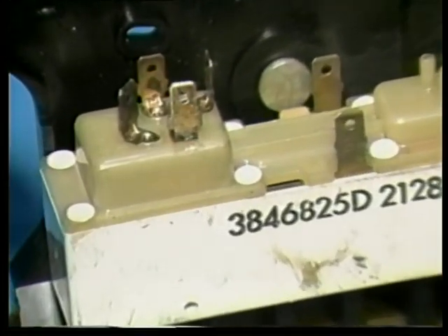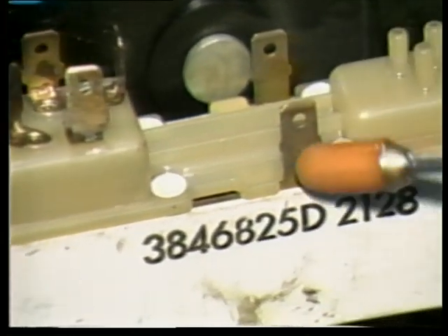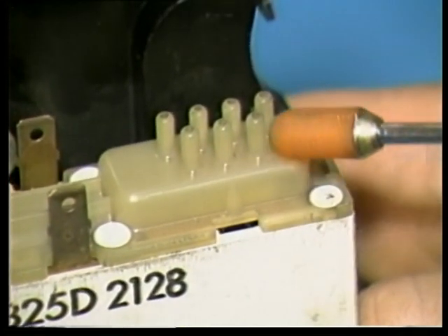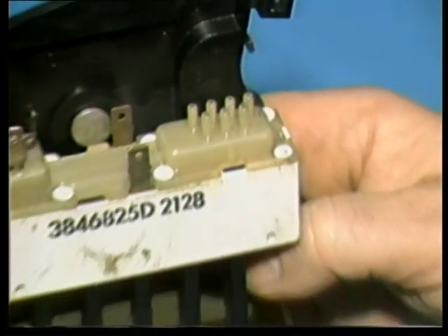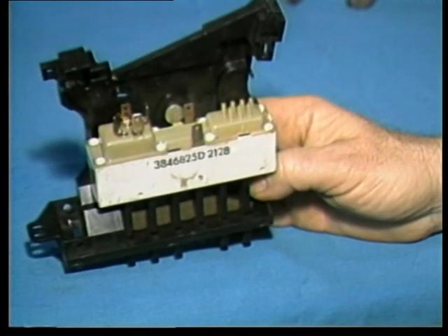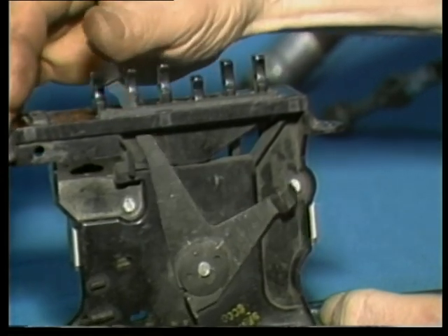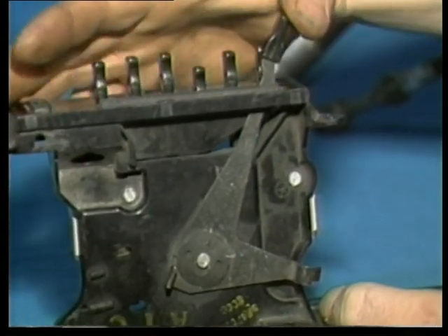The rear of the control panel shows electrical terminals for the blower motor, the compressor clutch coil, and vacuum connections which use rubber hoses to route pressure to the vacuum diaphragms that operate the air doors. Note how when you move the temperature selector, it moves a lever which would be connected to a control cable.